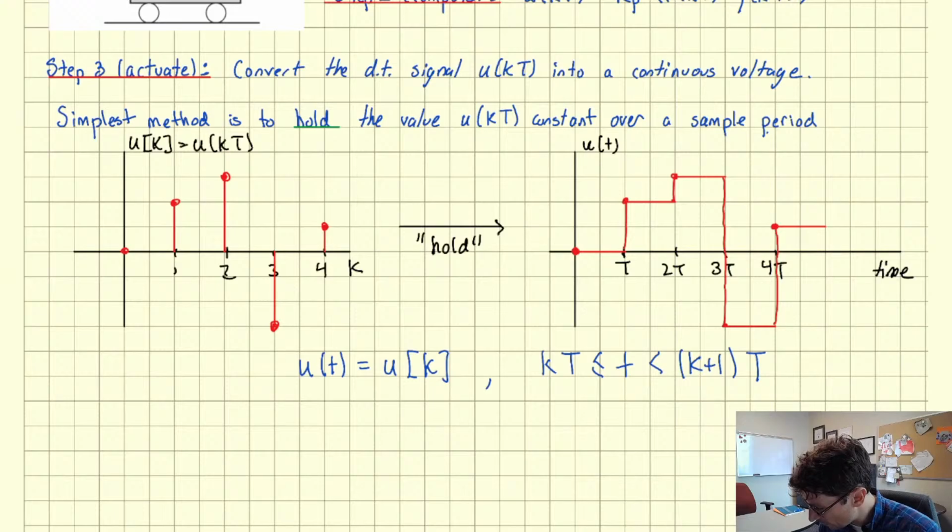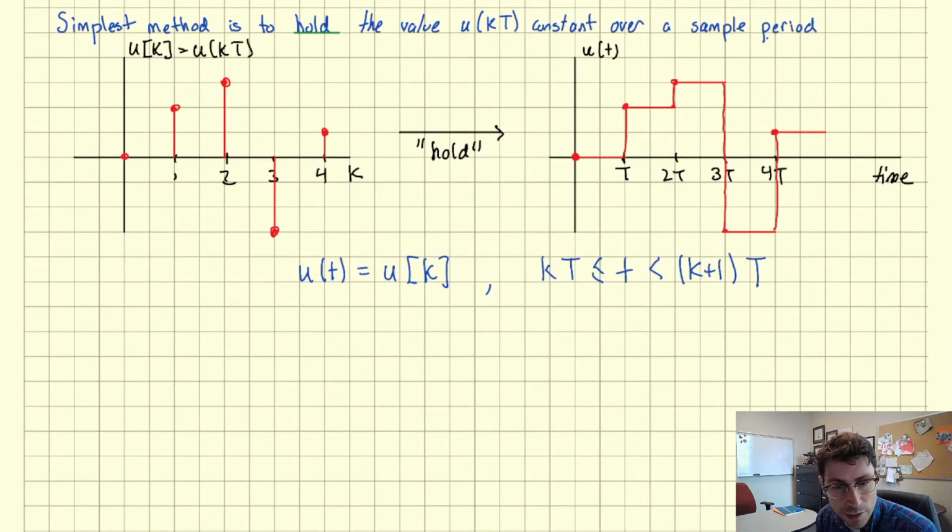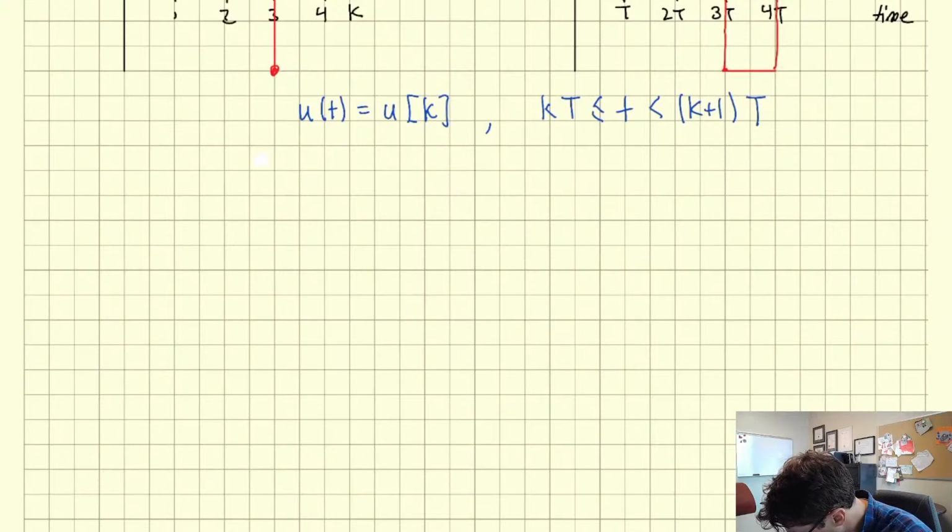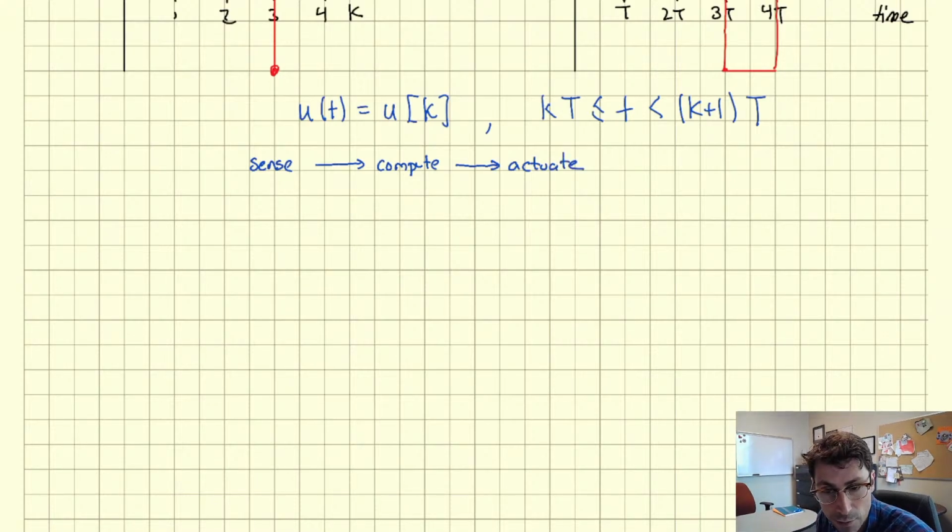Okay, and so again, the basic idea of this feedback loop, like any control system, is the following sequence of events. Sense, compute, actuate, right? So read the sensors, update your control value, and then actually do something for the physical system, and then repeat that. That idea right there is the central idea in real-time control.